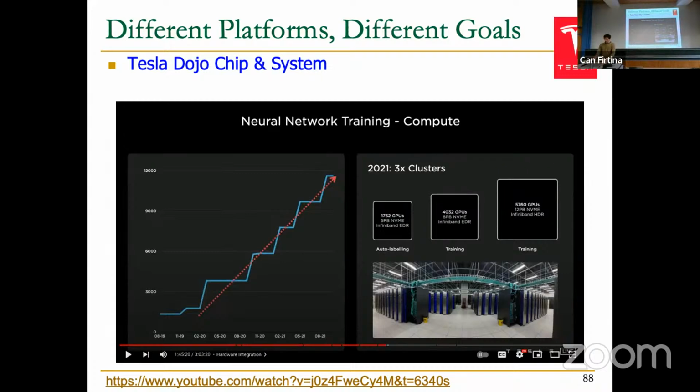Why is that? Because the accelerator is designed for a specific type of workload, that is deep neural networks. If you go to a deep neural network and you analyze how it's implemented for a CPU or for a GPU, you will see that most of the layers can be lowered, can be transformed into a matrix multiplication. So if you are targeting an important class of applications, important for multiple reasons, right? Neural networks are everywhere these days, and you want to accelerate them, it might be a good idea to create a specialized architecture for this specific workload, right?